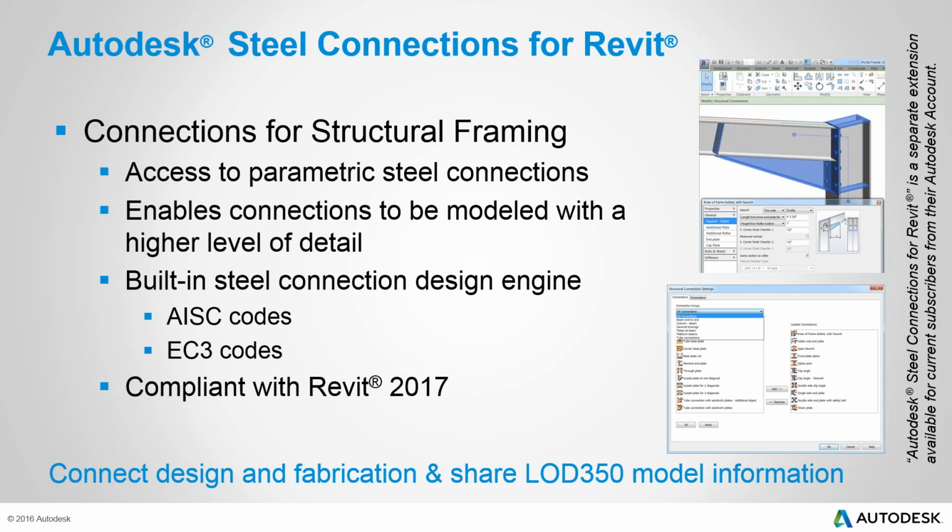There are 22 in there at the moment, whereas Autodesk Advanced Steel has around 220 odd. At the moment, Revit has 22 of them. I have spoken about this on YouTube, and I think there are a few articles floating about in the AKN showing how these are created and how you synchronize them back and forth. There are obviously workflows to stick to in here. Starting the connections inside Revit just means that we can export them and then synchronize them back.